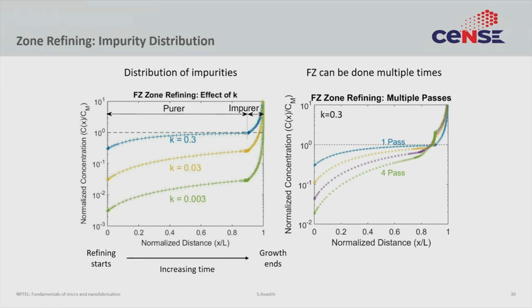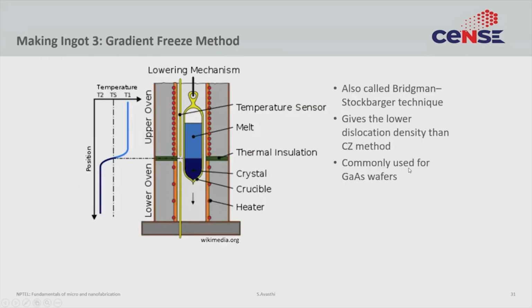This again means that for niche applications where you want extremely pure silicon, float zone is much more interesting. If you try to do this with CZ silicon, it would not work because you are melting the whole boule.